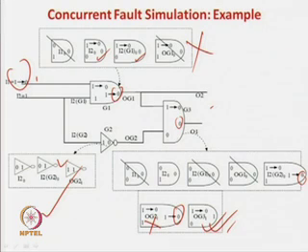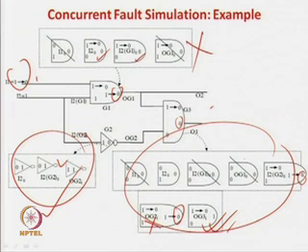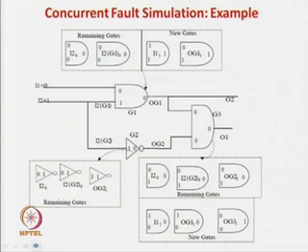But what essentially we have done is that we have retained this gate directly without going for any kind of additional computation, and in this case also we have gone for some computation, but the computations are minimal. Here actually we did not do any computation, but still directly we can find out that we can delete it. In this case only these small computations, which are pointed out, we have to do, and then we can find out the fault place. So, now after doing this, we have just said that these are the remaining gates, these are the remaining gates and these are the remaining gates.